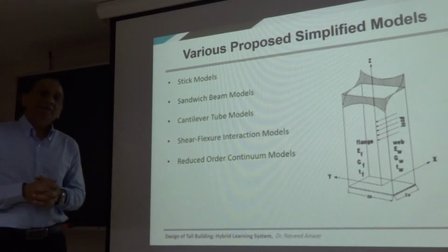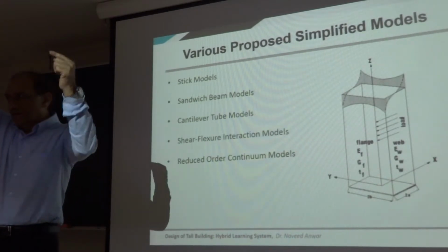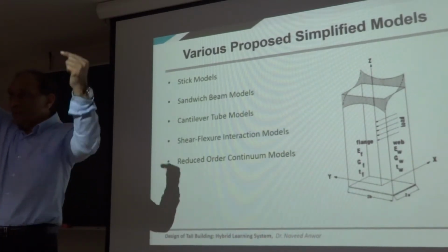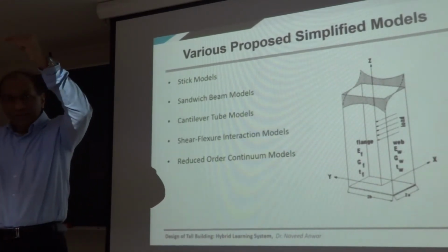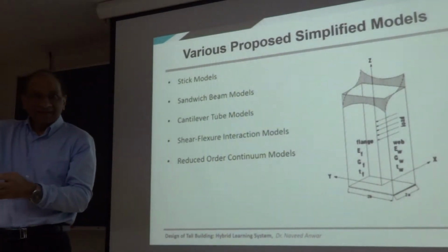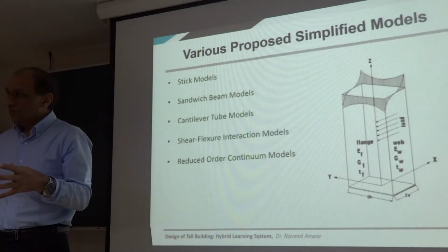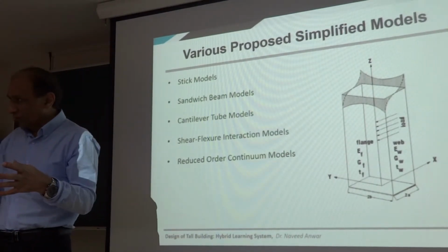It's just like taking a single column, putting a horizontal load there, calculating the bending moment, and finding out how much reinforcement you need. So an individual bar you can assume as a column, right? And the rest of the concrete as your floor. So you can